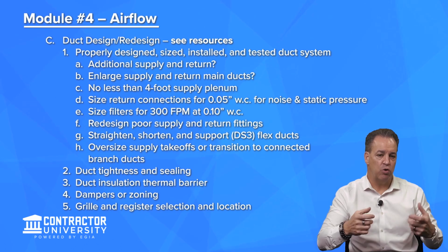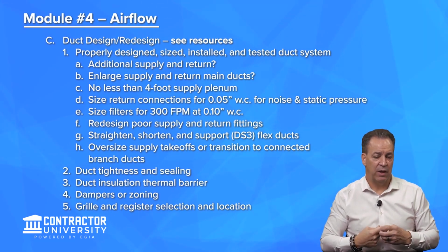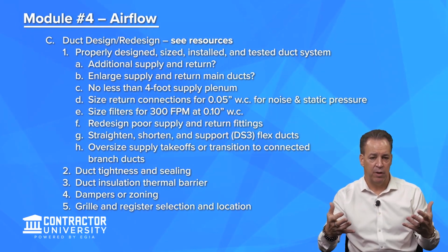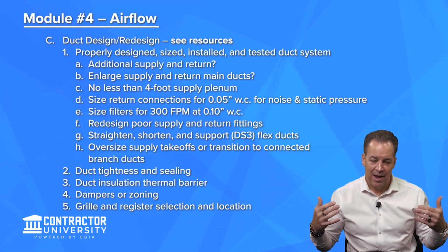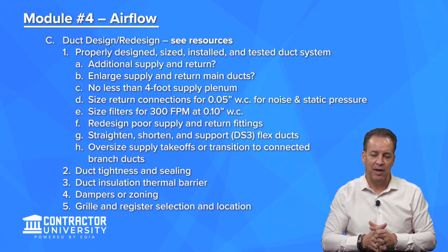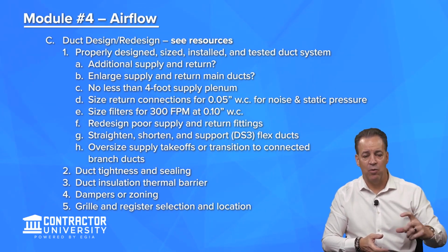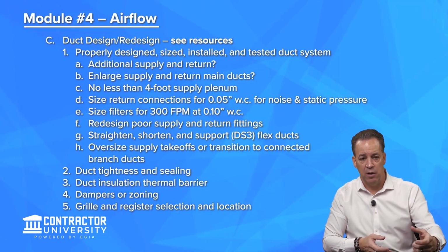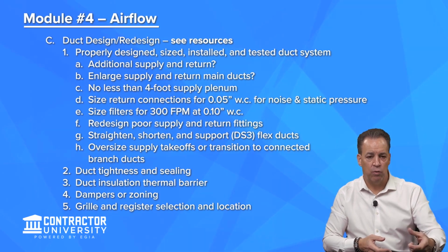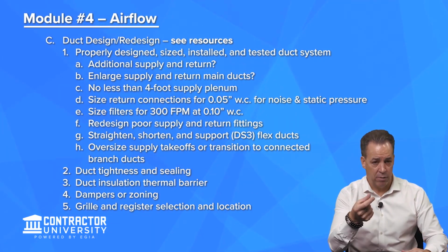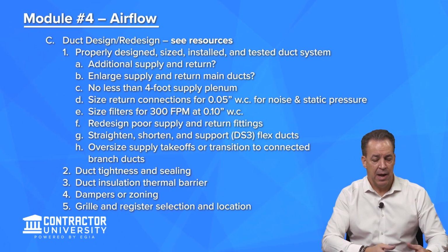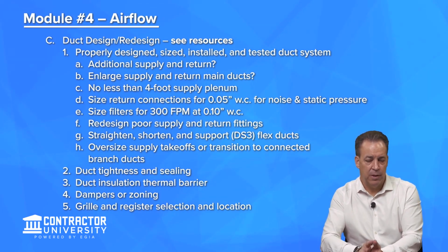And I like to use commercial grade grills nowadays because they're less restrictive and they allow that air to flow a little bit more freely, especially with these high efficiency, advanced technology, variable speed fans. And so I'd rather change out the ones that they have there. And if I'm putting in new, I'm going to put in new commercial grade grills that have wider spacing between the louvers. And then registers and diffusers.